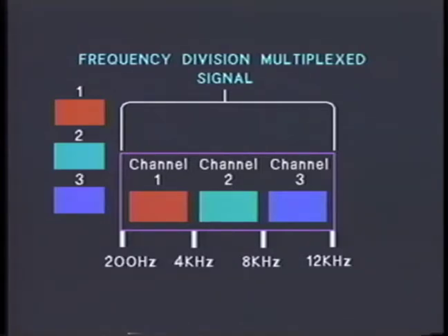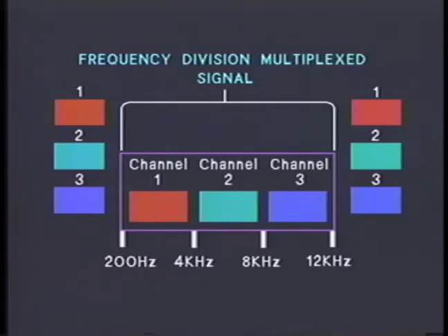To frequency division multiplex, the frequency of each input signal is boosted to fit into one of the channels. The signals share the same transmission path as the composite signal. After transmission, the demultiplexer uses a filtering process to separate each channel. Then the demultiplexer returns each channel to voice frequencies to restore the signal to their original form.